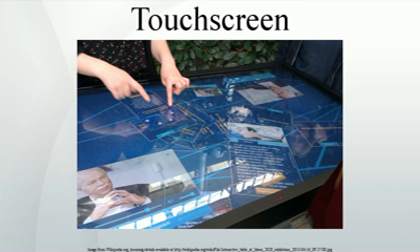The technology differs from other attempts to recognize the position of touch with transducers or microphones, using a simple table lookup method rather than requiring powerful and expensive signal processing hardware to attempt to calculate the touch location without any references. As with the dispersive signal technology system, a motionless finger cannot be detected after the initial touch. However, for the same reason, the touch recognition is not disrupted by any resting objects.